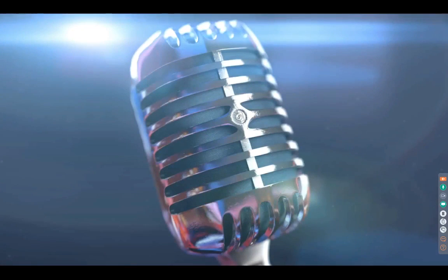So what makes the Unidyne element special is we created rejection. We created a unidirectional microphone utilizing one element, and the way we do that is we allow sound to strike not only the front of the diaphragm but the back of the diaphragm as well, and we delay that sound just a little bit. And here's the animation that we'll show you here.